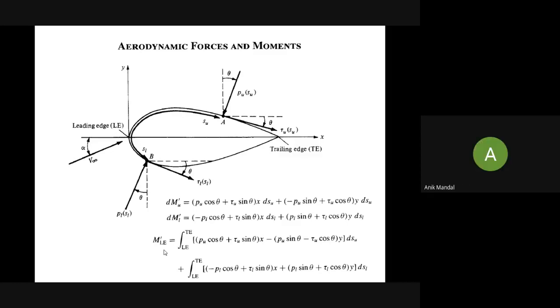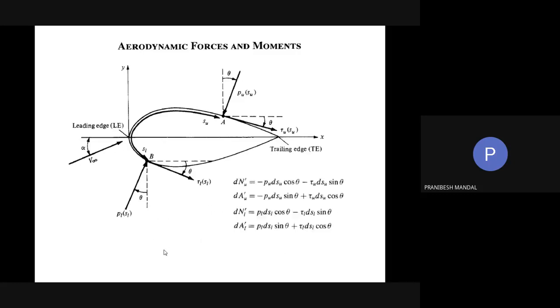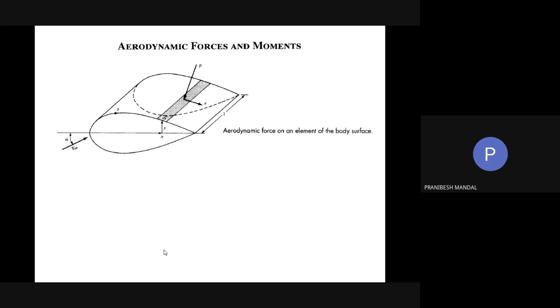Yes, sir. See, aerodynamic guys are very much alarmed about the assumptions, because aerodynamics is very much affected by assumptions. So they used to take the assumptions in the notations also. In this particular case, we have considered a unit depth of this particular aerofoil section, right? The span is unity as it is told, but in a practical case, is it unity always?